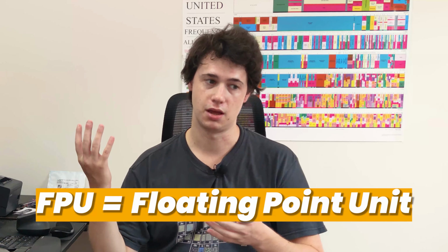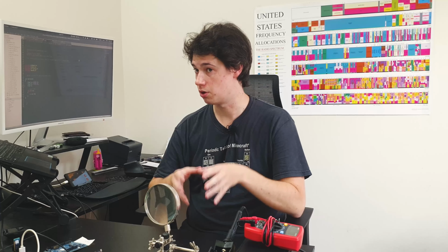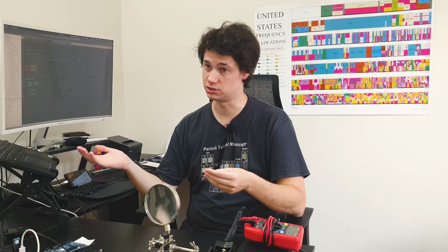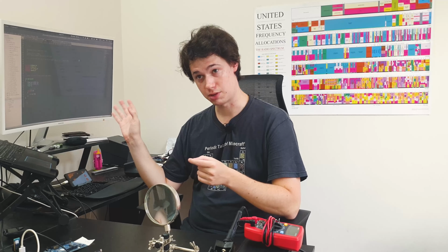An FPU is a processor with some specific instructions that is able to do calculations on floating point numbers. Cheaper microcontrollers are not gonna embed such a device because that saves costs. But more advanced microcontrollers are going to have an FPU and are going to be able to do an addition between numbers with commas in them as easily as regular integer numbers. The precise microcontroller that I'm using does have an FPU, which allows us to use it or not if we want, and that way we can see the compiled code and the differences between the two generated ELF files.